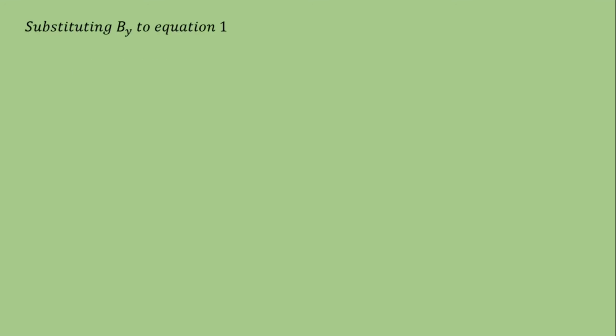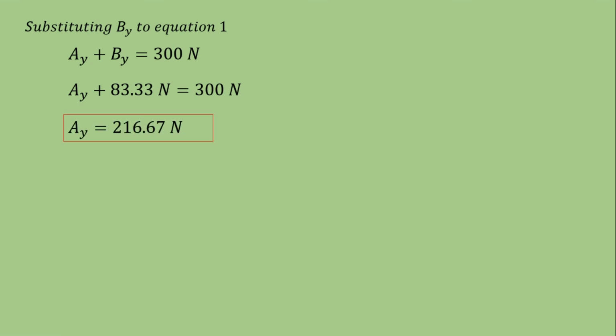Substituting the vertical reaction at B into equation 1, we get AY plus BY equal to 300 Newton. So AY plus 83.33 Newton is equal to 300 Newton. This will result in AY equal to 216.67 Newton.